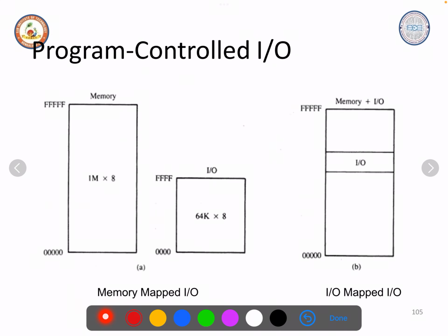So instead, we can have a different technique without waiting for the input or output device to become ready. Processor can keep on doing its work. Once the device itself is ready, that device will send a signal saying that I am ready to send the character or I am ready to receive the character. Then the processor will in turn send a signal, data to transmit.